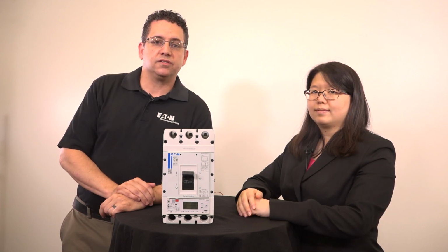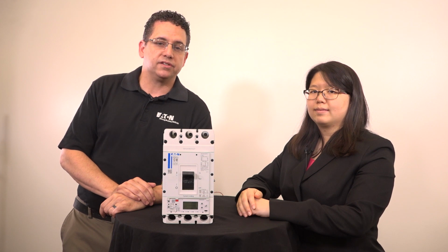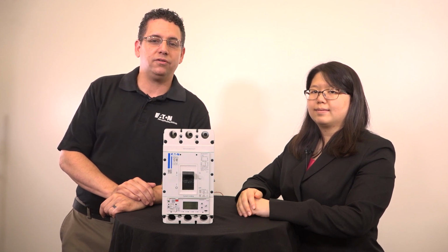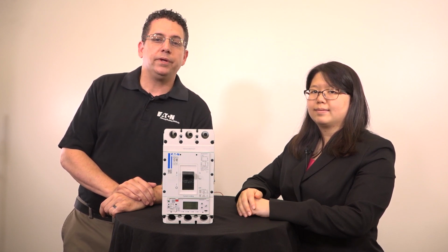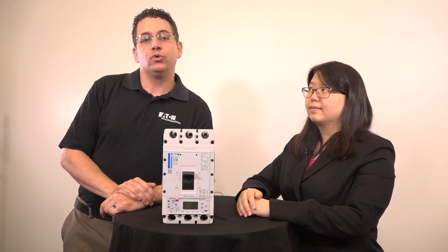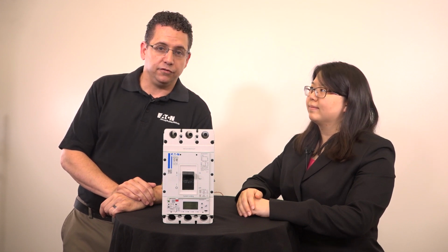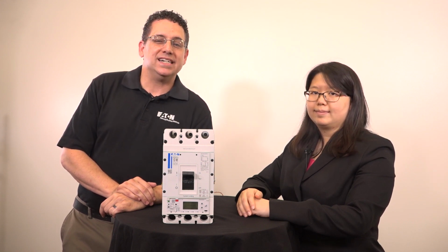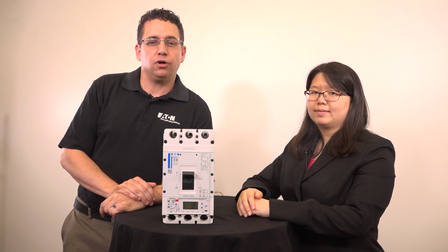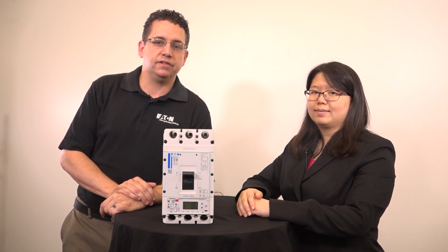By resetting the diagnostic data, you're deleting the breaker memory of the various faults that occurred throughout its life. Not only do you lose all the history, your breaker health will appear artificially high. Resetting the diagnostic data will not extend the life of your breaker. It will give you an inability to monitor it. So don't reset the diagnostic data unless you have specific guidance from your user manual.